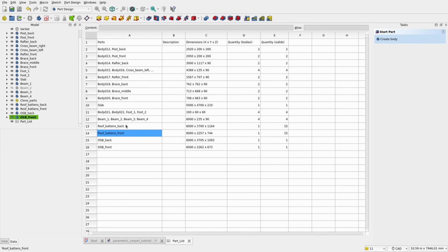This can be super helpful if you're making cutting lists. Just keep in mind the values will only be correct if the object is lying flat. If the part is rotated, the dimensions might be off. You can download the macro from the link in the description.